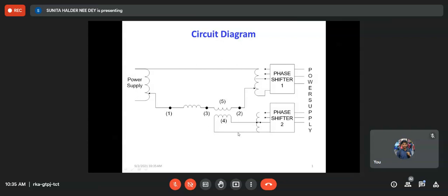But if you perform this experiment in the laboratory, you will not get so much control. A number of readings will not be available. We can hardly get one set of readings, but that is not at the same point. Every day it will change, because every day the generation voltage from the supply changes to some extent, and obviously it depends on at which point in time you are performing the experiment. When there is load in the system, whatever you are using has an inherent phase angle, an inherent load angle, and that also affects the experiment.